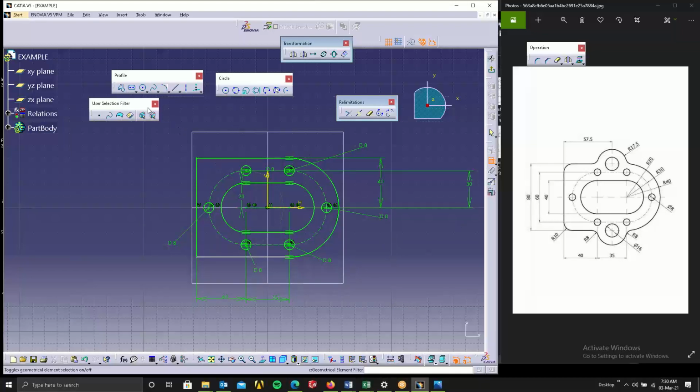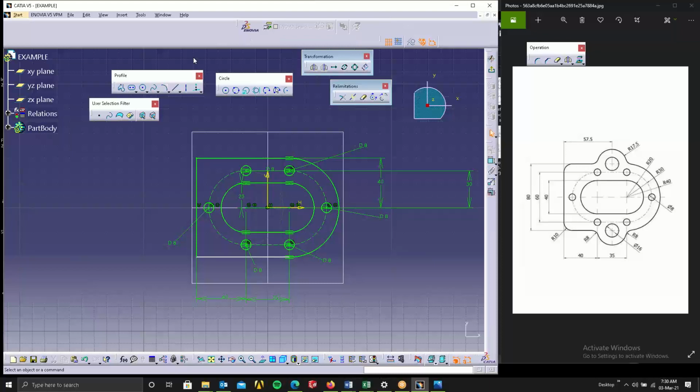We have this fillet over here. So what I can do is straight away use the fillet. The operations are over here. So you just select your fillet, select this thing, select your fillet over here and just go to your sketch tool. What is the value of the fillet? It is radius 10. Select R10 and you can get the radius of the fillet.